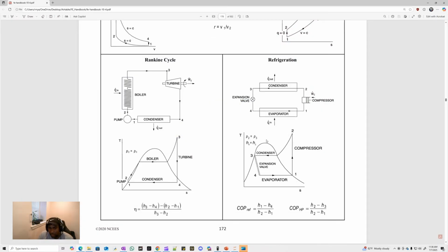Okay, I also had up a TS diagram here if you wanted to see a cleaner schematic and emphasize that the coefficient of performance we're finding is exactly what's in the reference manual. It's the desired output. The desired output is just the difference between H1 and H4. That's the heat in from the low temperature source, and the required input is the work into that compressor.